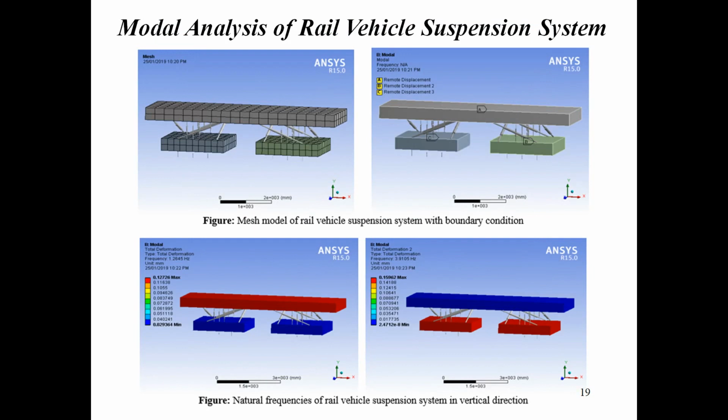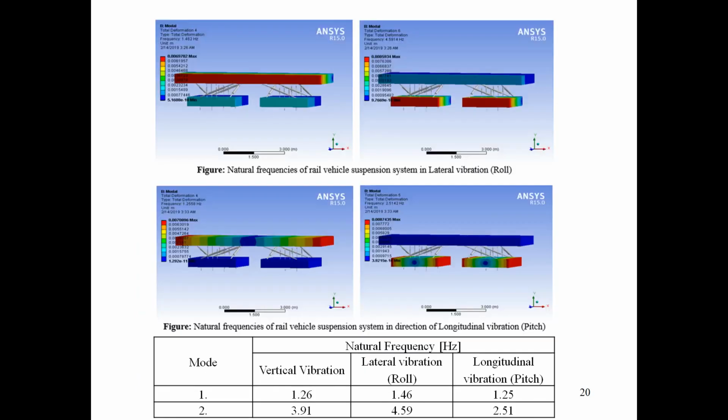Modal analysis indicates that we don't have to apply any load. We just fix the body at any one side, and you will get the frequencies. For example, a tree is fixed at the ground, and it is free at the top edge, where the leaves are moving here and there. These are nothing but free vibrations, or we can say it is freely moving anywhere. So the displacement can move in any direction without applying any force. Okay, so that is the modal analysis.